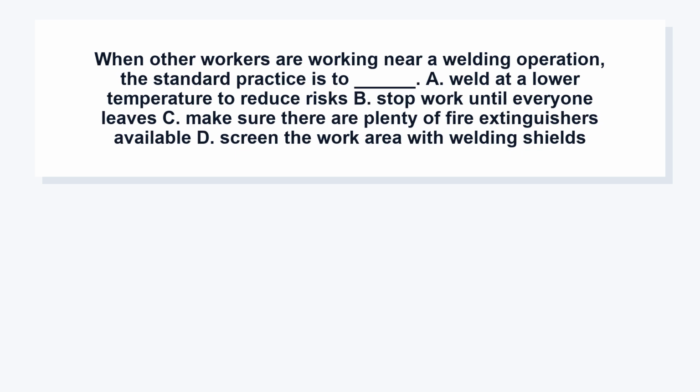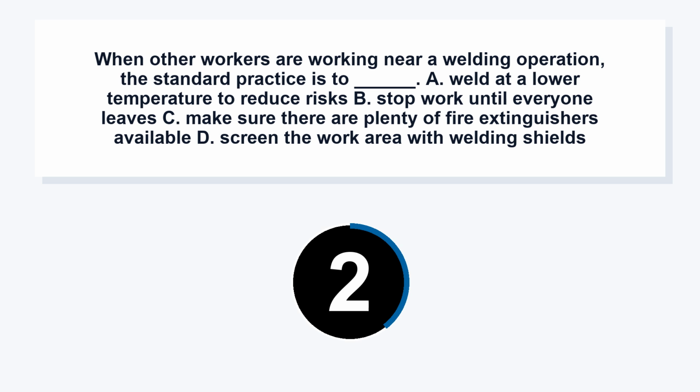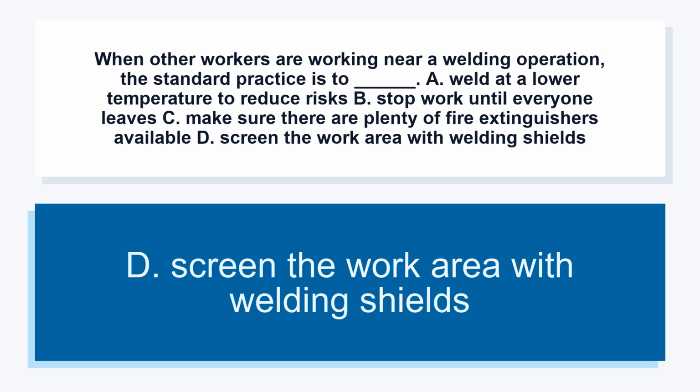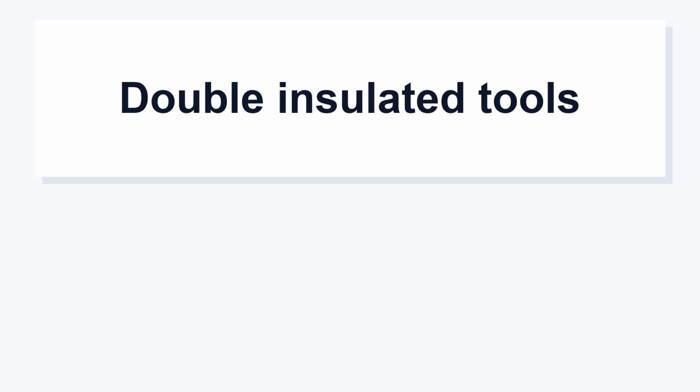When other workers are working near a welding operation, the standard practice is to: A. Weld at a lower temperature to reduce risks. B. Stop work until everyone leaves. C. Make sure there are plenty of fire extinguishers available. D. Screen the work area with welding shields. D. Screen the work area with welding shields. Double insulated tools.